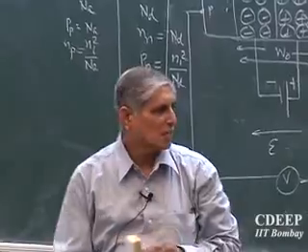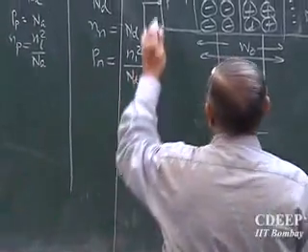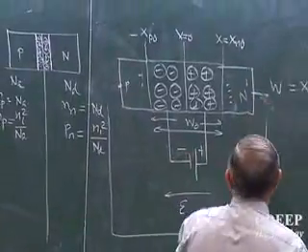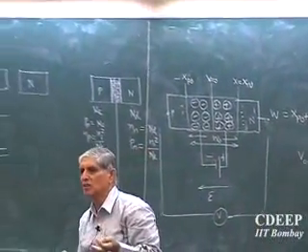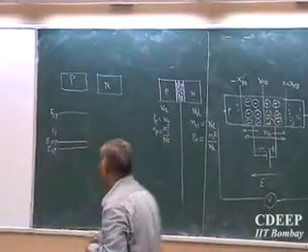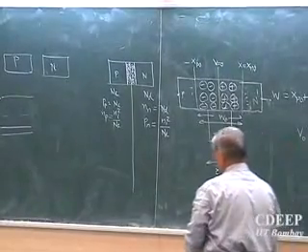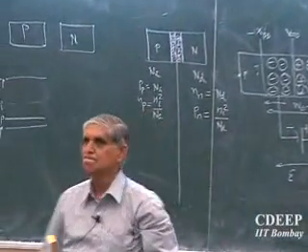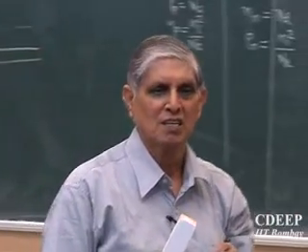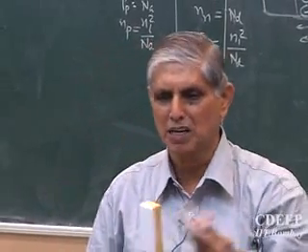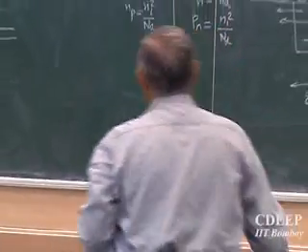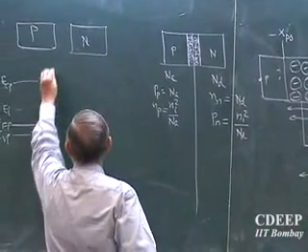Let us start thinking. In this semiconductor, if I don't connect anything here, even a voltmeter has infinite impedance, so it doesn't pass any current. Right now there are no currents here. If there is no current, what is the theory we suggested for the Fermi level? The Fermi level must be constant across. Is that correct? So between P and N, the Fermi level must align because there is no current between P and N. Okay. So let us say this is my junction.